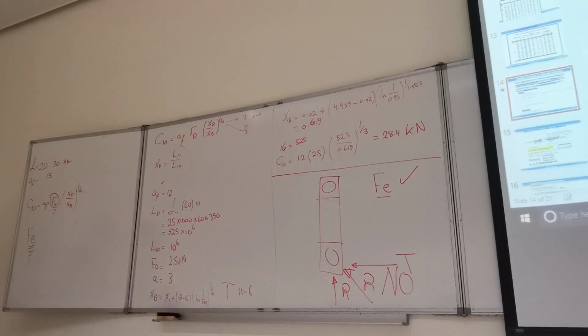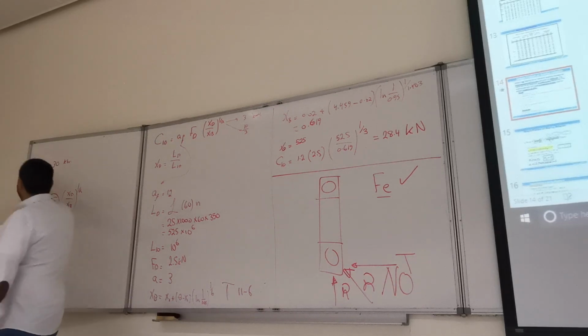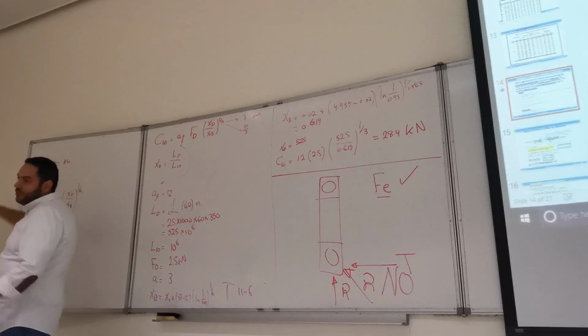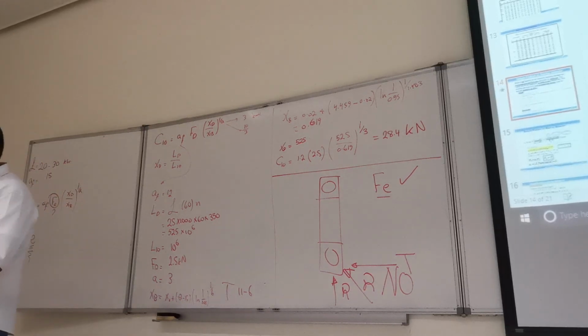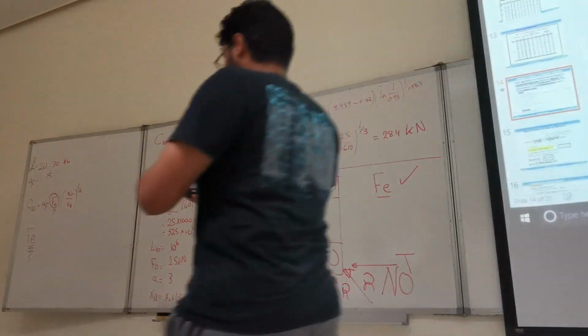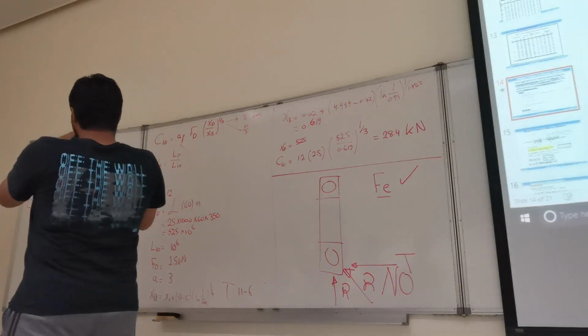Safety from the table. Yeah, this is the line, from continuous 20 to 30 kilo hours. If you open the table, for 8-hour service, continuous from 20 to 30 kilo hours, we'll pick a value from that. It's just like always. If you are conservative, you go with a high value, and if not conservative, you go with a low one.